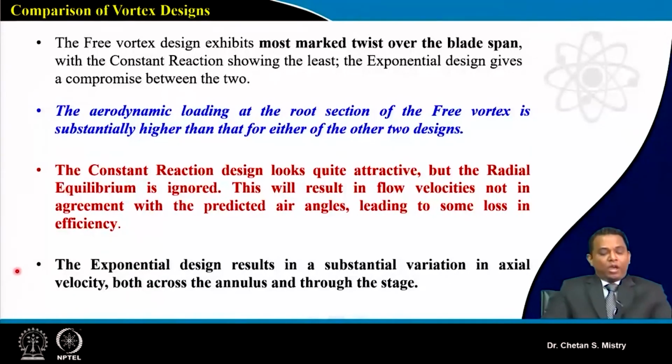Okay. Now the exponential design has a challenge in terms of variation of my axial velocity, across the stage as well as near the annulus. So this gives you a whole lot of options for the design, but it's up to you to decide how you will approach your design aspects.